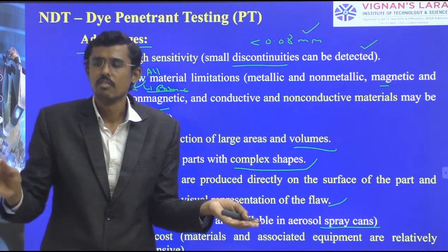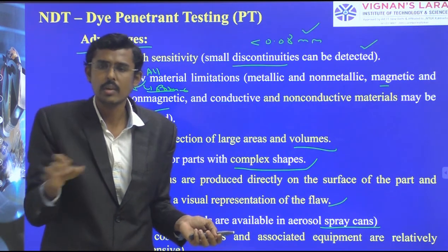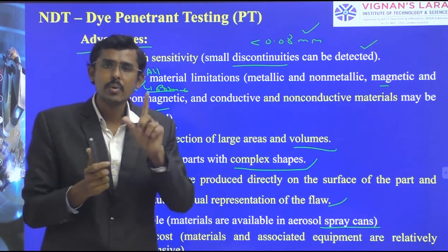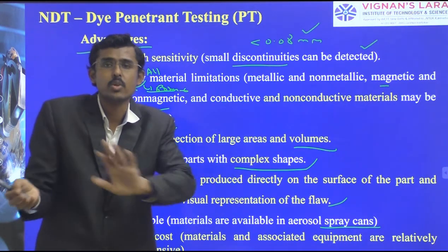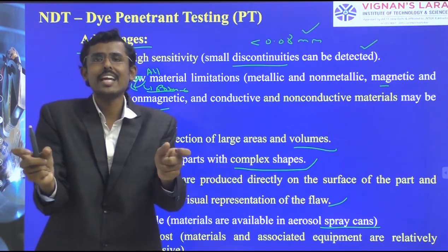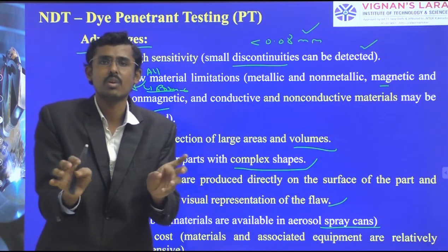First pre-cleaning, then applying penetrant, dwell time, then cleaning, then applying the developer, and after inspection, post cleaning. So only two cans with some cloths.